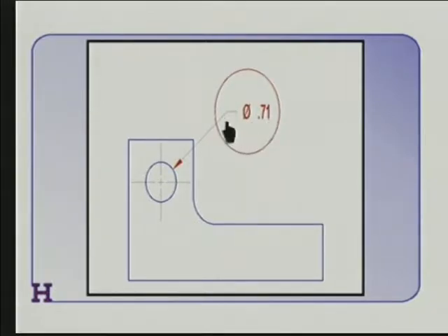In this case, we're using a single arrow. We'll show you a little later how diameters might be dimensioned in the longitudinal view. In that case, we have a standard broken dimension line with 2 arrows. But in either case, we use the diameter symbol followed by the numerical value.